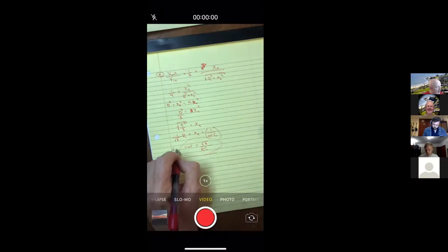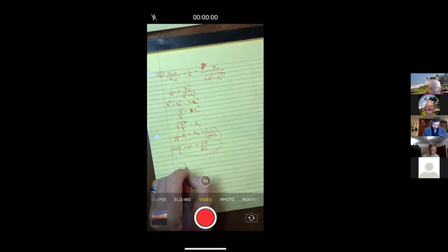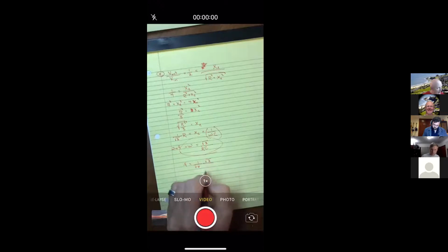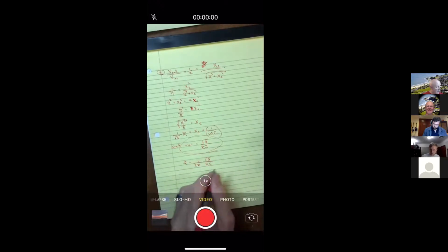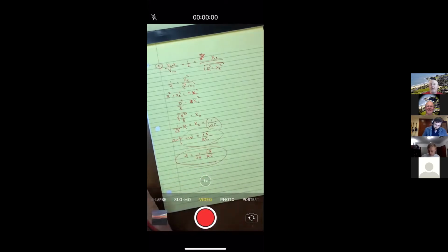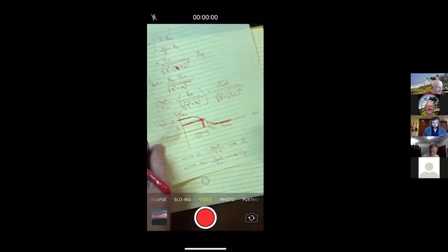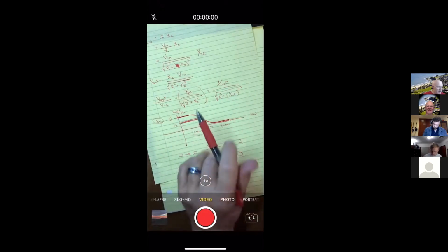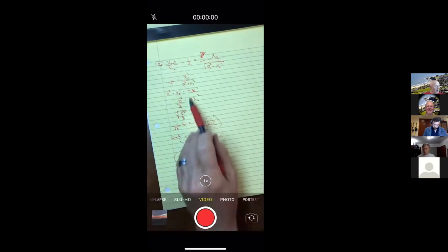They said omega is 2 pi f, okay? So that's always a little confusing if they mean angular frequency or frequency. I interpreted it as angular frequency, and I shouldn't have, because they said frequency. So let me replace the omega with 2 pi f and bring the 2 pi over. So they got the square root of 3 in the numerator to 2 pi and an RC in the denominator. And I can only imagine that solving for omega with this compound fraction, getting a common denominator, squaring it would have been way harder than just those steps.